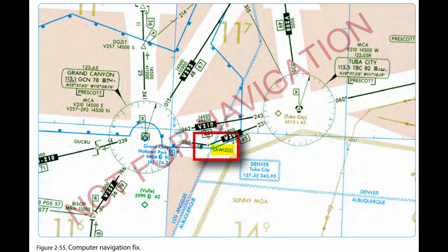RNP capability of the aircraft is a major component in determining the separation criteria to ensure that the overall containment of the operation is met. The RNP capability of an aircraft varies depending upon the aircraft equipment and the navigation infrastructure. For example, an aircraft may be equipped and certified for RNP 1.0, but may not be capable of RNP 1.0 operations due to limited navaid coverage.